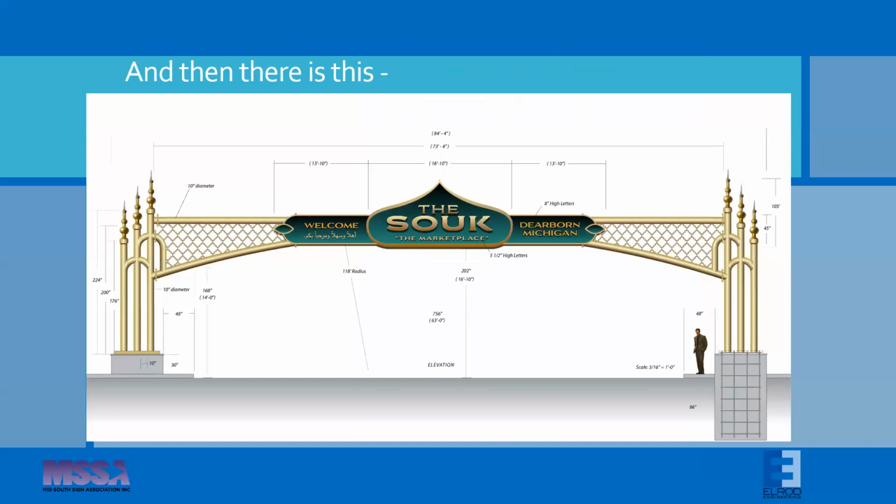Freestanding signs can get pretty interesting. Architecturally, this gateway sign that we designed looks really good, but once we got into analysis, we realized that there were some issues as to how the load of that center sign is transferred through the vertical support poles. Engineers always get accused of over-engineering things, or often we get accused of over-engineering things. And so when we realized this, the first thing we wanted to communicate to the client was that approximately 85% of the load of those signs is going through the center poles, those two innermost poles.